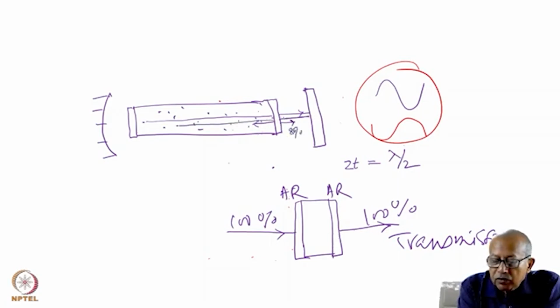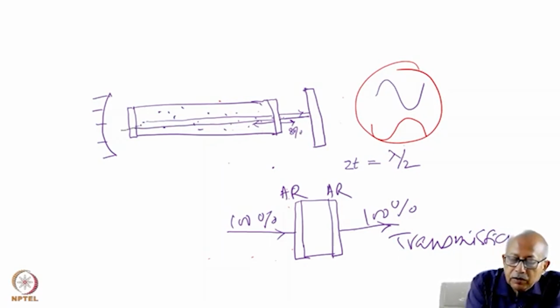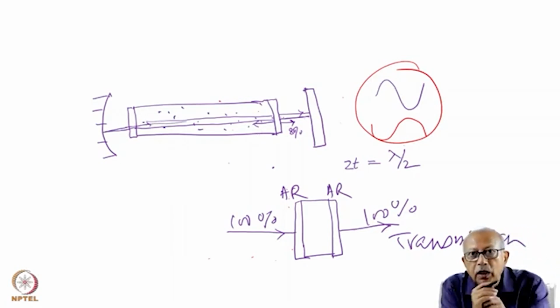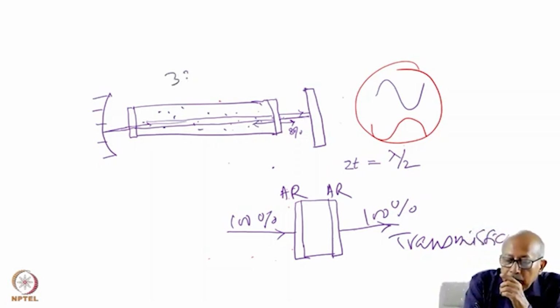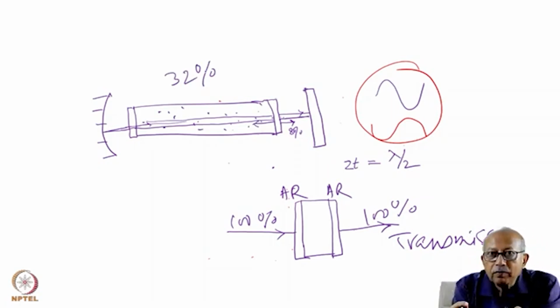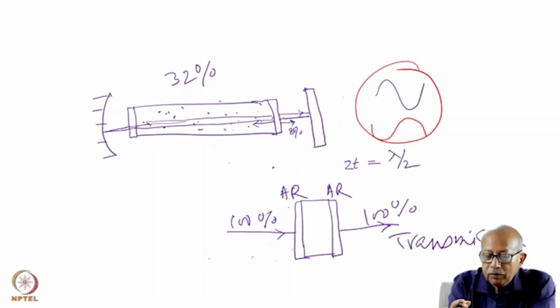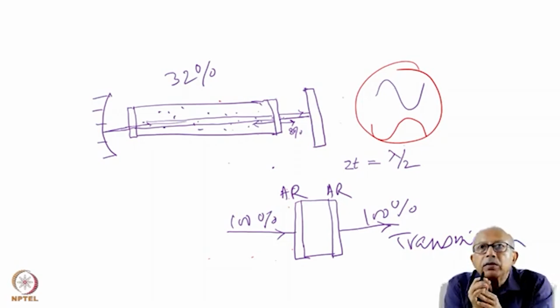Again 8% will be reflected, and after the reflection comes, again 8%. So in a to and fro journey, if you use an ordinary glass plate, 32% of the light which has been generated would simply be lost through this reflection. So you can't tolerate such a reflective component in your sealing optics, which will seal the two ends of this gas cell.